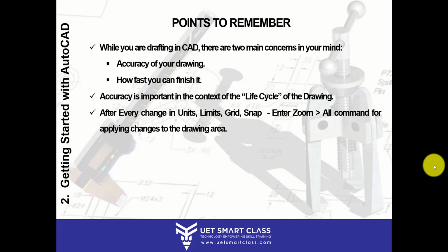I mean, you can draw rectangles very fast with the rectangle command rather than going for a line command or a polyline command. But sometimes we cannot draw that particular object using a rectangle command, even if it is a regular rectangle. We have to draw it with a line. You will understand the difference, and I will give you a few examples when we do this rectangle command.